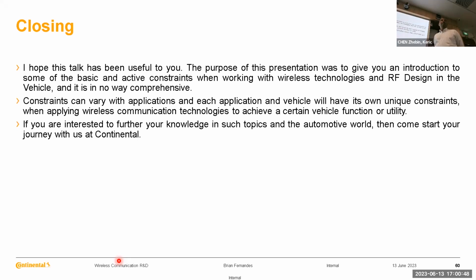Yeah, so I think typically if different standards coexist, it's a challenge for us. But the reason they coexist is because different countries allow certain parts of the spectrum to be used openly for certain standards. That means anybody who has a wireless technology they want to implement is constrained to that band of spectrum. That's usually why you have so many different standards operating, because you have a lot of different functions. You have technologies that give you long distance communication, and technologies that are very good for short range and very high efficiency.